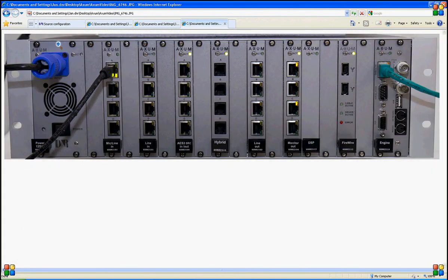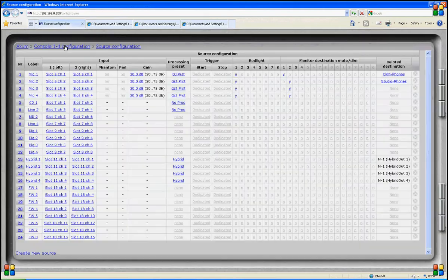We said that the mic input 2, 3 and 4 are also located on position 5 and on both left and right. All sources in this mixer are considered stereo. However, a microphone is mono, so both inputs left and right have to be assigned. In this way the microphone is mono but assigned as stereo source.